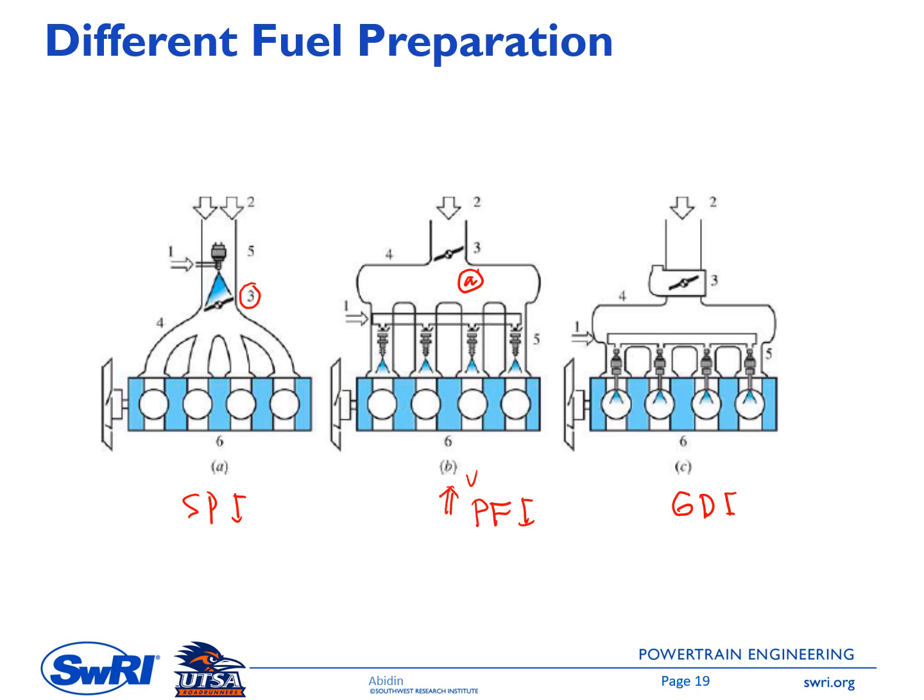Compared to, let's say, A here, if you change the load, it will take time for the cylinder to respond to the change of the fuel, because there will be a delay due to the distance from this one to this one. This one will have the best transient response, and this one will be second. We will have a detailed analysis of PFI and GDI in chapter 7.